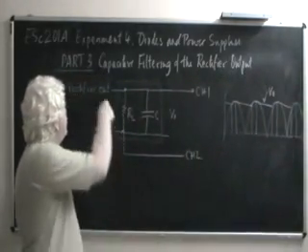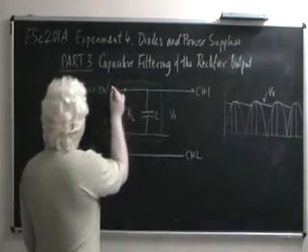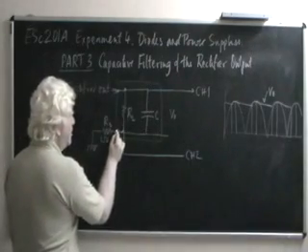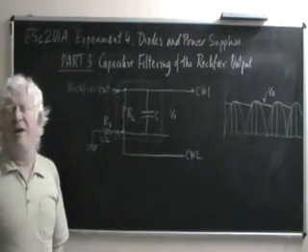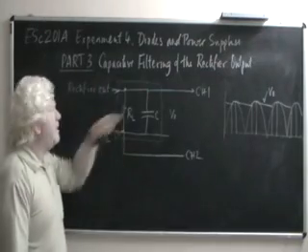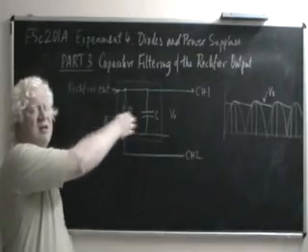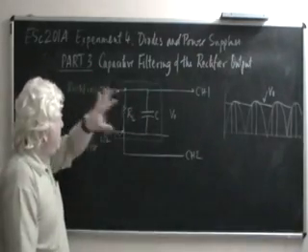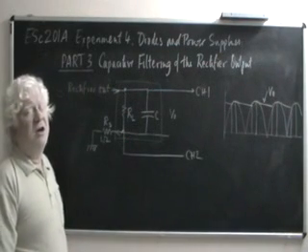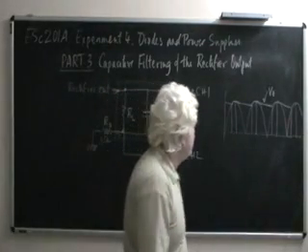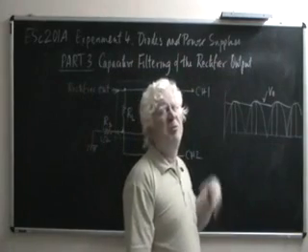So it's only when the diode is forward biased that it can conduct current. And if it is the diode current that's coming in here, it is the diode current that's going out here. The resistor itself will carry current for a longer period of time, but that current is being sourced by the capacitor, not to be measured through Rs, because Rs is outside the resistor capacitor pair. So this pair consisting of resistor and capacitor only allows a current to flow in for these short intervals of time, and during these short intervals of time a current will flow that is approximately proportional to the voltage.